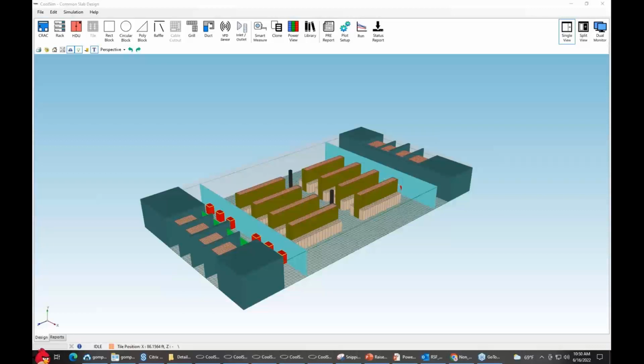But it's been coming down because the servers are becoming more efficient in terms of their heat dissipation. So their appetite is a little lower for CFM per kW. So now it's down around 100 and seems to be dropping. In other words, they're getting better and better at that.